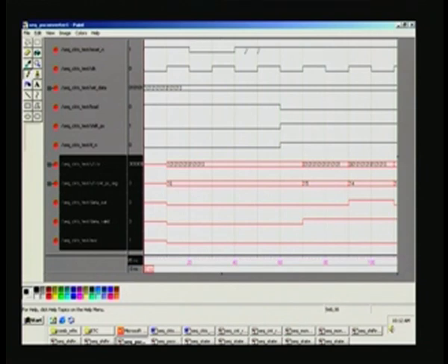As usual a reset is applied, and this is set data. Here also we are setting the same 1010 pattern. What happens internally is there is a 16 bit shift register, and that is preset to the same 1010 because that is what we want, and at the positive edge of the clock, because code has been written like that, and this is the counter to keep track of the number of bits.